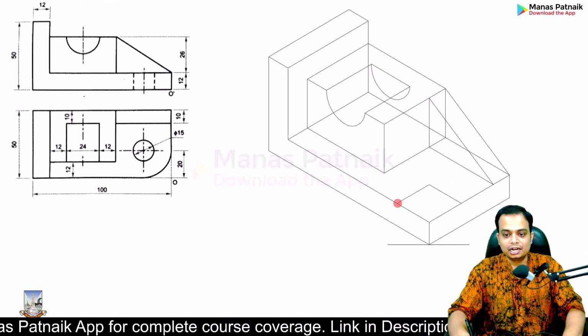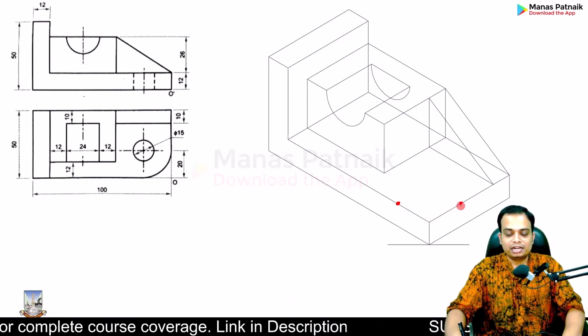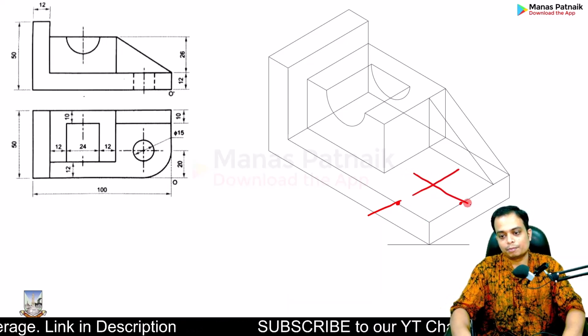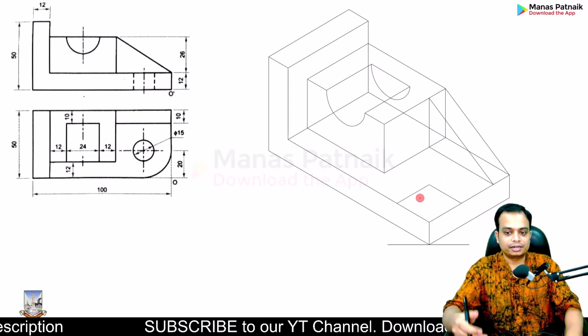It's very easy. Let me tell you. So what you can do is you can make 2 points, 20 millimeters, 20 millimeters. Then draw parallel lines with respect to this. Draw a parallel line. The intersection is going to give you the center. Very easy. Here it is.